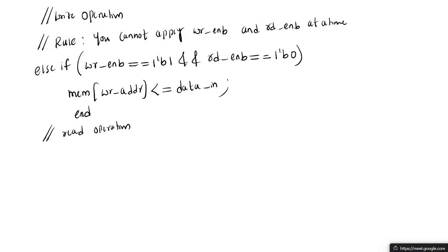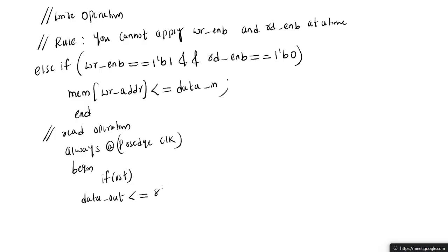The read operation is always at the positive edge of clock, begin, if reset, begin, data_out equal to 8'b00000000. Okay, else